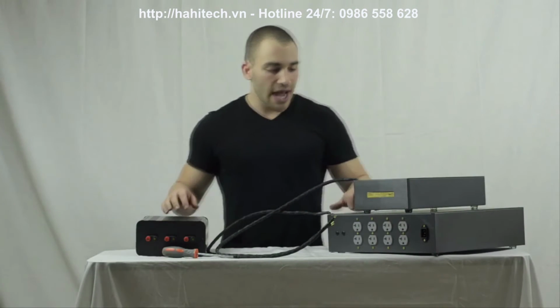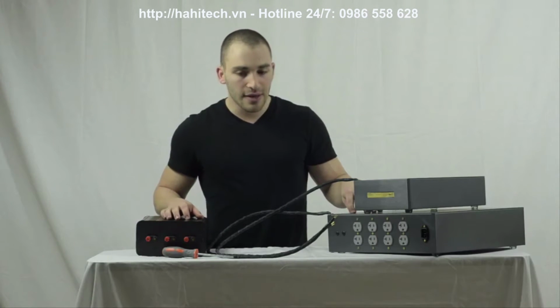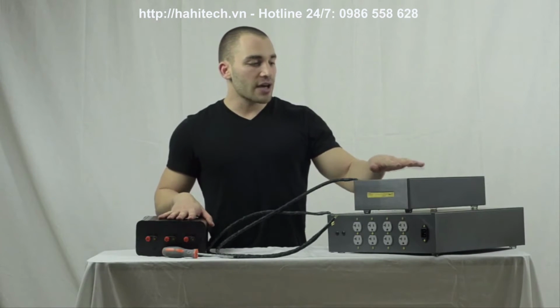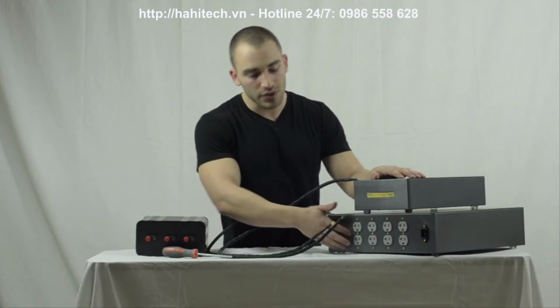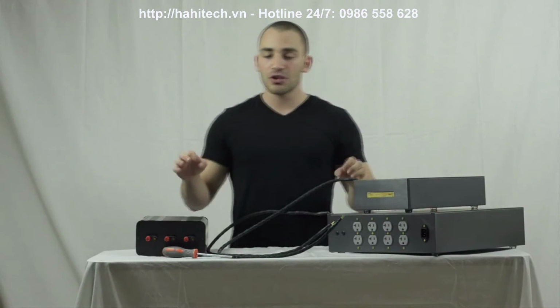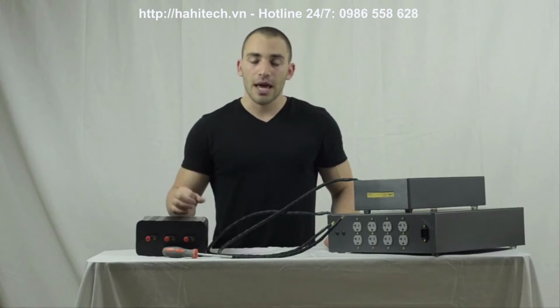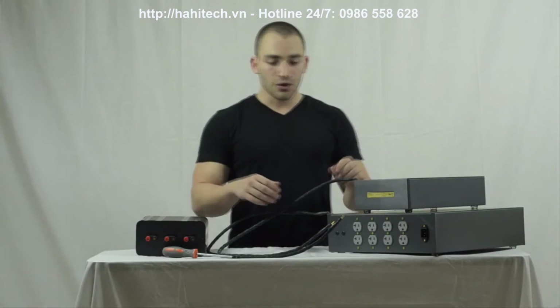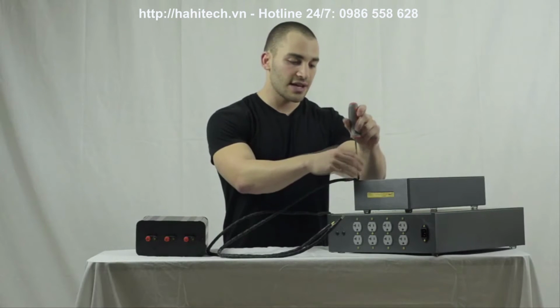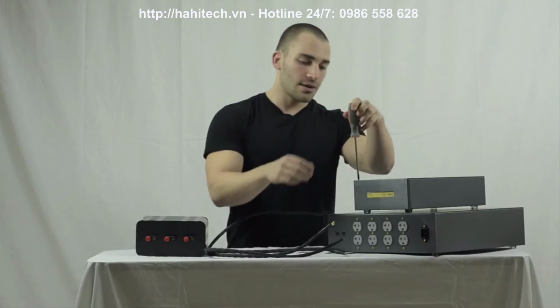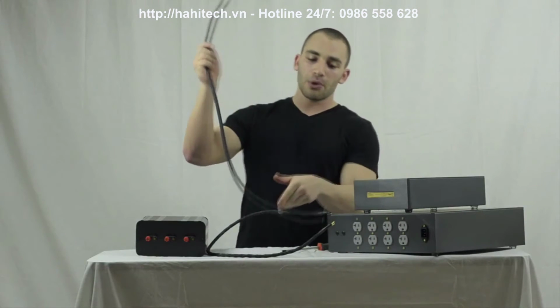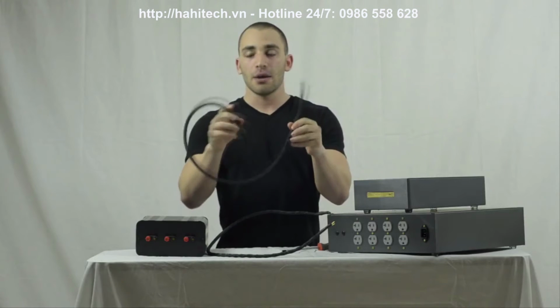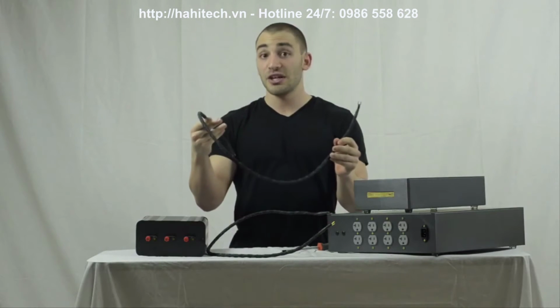There's a couple other things that happen when you're looking at audio system grounding. When you have a common impedance issue between components created by voltage mismatches on the ground, you end up introducing noise currents that flow along the shield that are introduced into the signal cabling. When you're looking at a signal cable, and we'll pretend that this here is a signal cable, even though it's just carrying a single rail, but we'll pretend that this is carrying both, let's say, a data line and a shield.